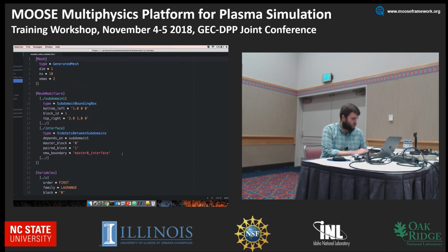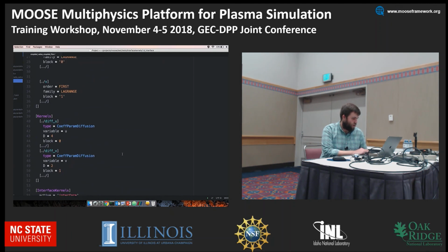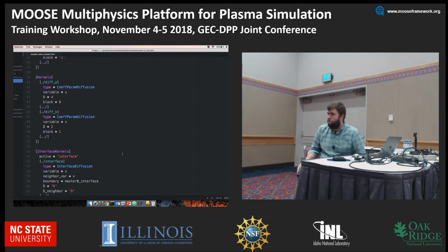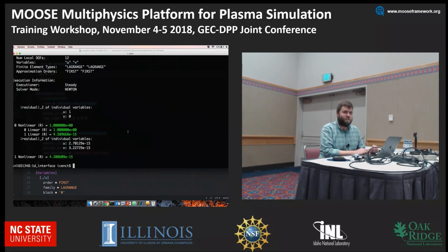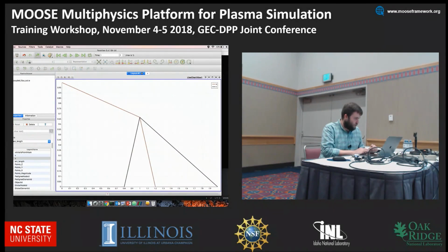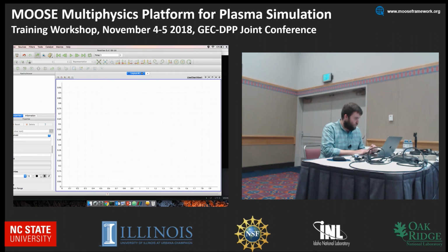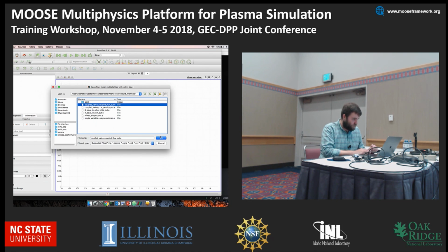Okay, so that may be an artifact of there not being very many mesh cells. Just to verify that, I'm going to increase the number of mesh cells, because I believe that's probably the case. Usually with these tests, you're running the most simple version that you can. So let's run this again, now that I've made that change. Then I'm going to remove this and reopen the file and see what we get out of the other side.